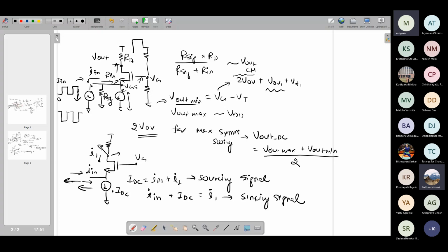So we are seeing that ultimately, if you're using an NMOS device as the input of the common gate, which scenario is better? If your polarity of the current is such that it is sourcing, then the best condition will be that you use an NMOS input device and let it source the current. If you use the PMOS version, the story will be just reversed. You can think of it. In the case of a sinking signal, a PMOS input device will work better.